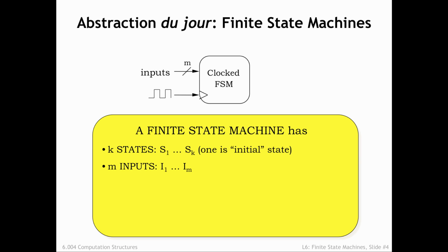In many real-world situations, where the sequential logic is much faster than whatever physical process we're trying to control, we'll often see the use of bit serial inputs, where the information arrives as a sequence, 1 bit at a time. That will allow us to use much less signaling hardware at the cost of the time required to transmit the information sequentially. The FSM has some number of outputs to convey the results of the sequential logic's computations. The comments before about serial versus parallel inputs apply equally to choosing how information should be encoded on the outputs.